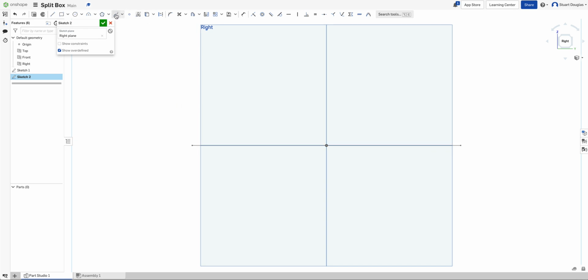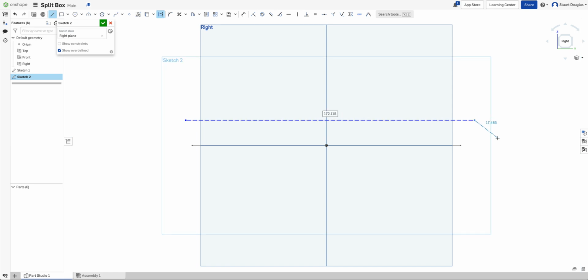What I want you to do is use the spline tool to draw a line which is basically going to be straight-ish, slightly curved here, but then go slightly bigger at this end, and an ever so slightly curved line on this side. But one thing we want to do is try and get an idea of where the height of that line is. So what we're going to do is change our line to a construction line. And I'm going to just start off by creating a couple of guidelines for me in my surface. So I'm just going to draw one, like so, and press escape.